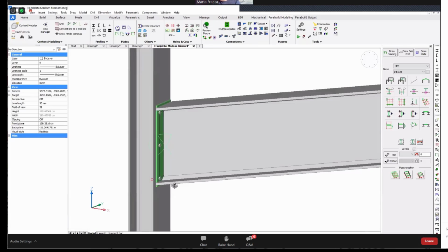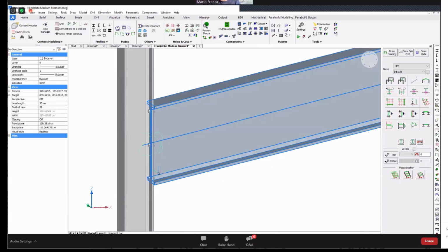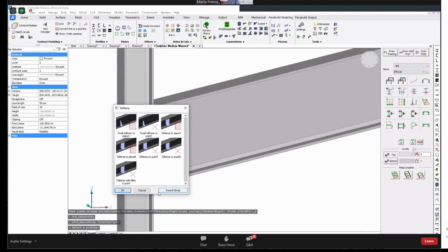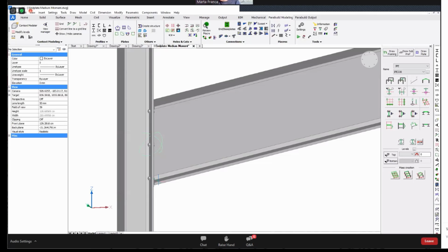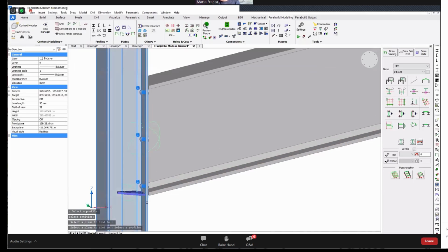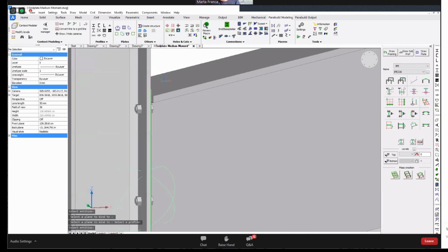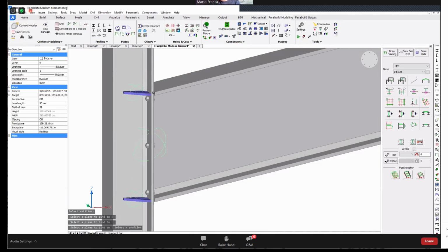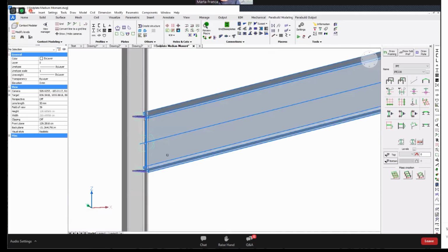And for this situation, just for the example, we would need more stiffeners. So let me add some stiffeners here. And I'm going to add these small stiffeners. Again, we can use plane, so this tool will work on any profile shape. And at the top, same. I am using the top face, so that face will be projected to my column for the position of the stiffener.